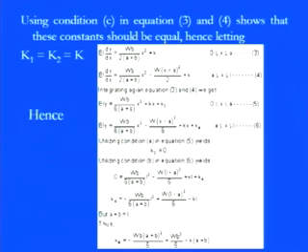So now you have the two different equations, the differential equations, and by integrating them we can get the slope conditions for the A portion and for the B portion, because as we just got to know, if you apply the load at a particular position, the slope will be equal for both of the sections, and the deflection is equal for both of the sections.